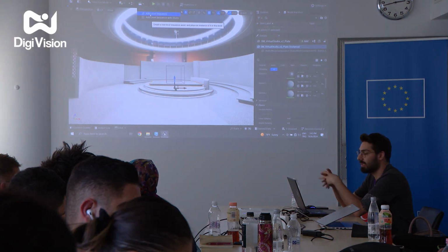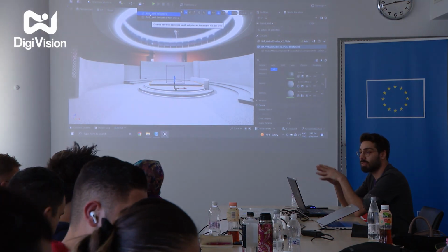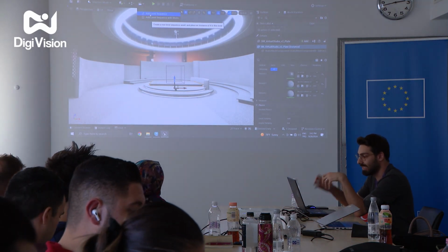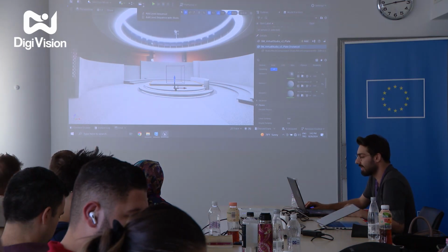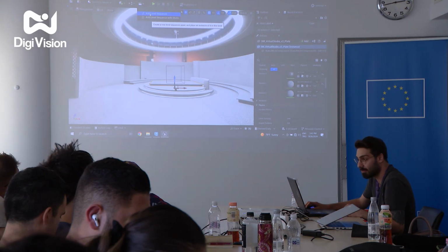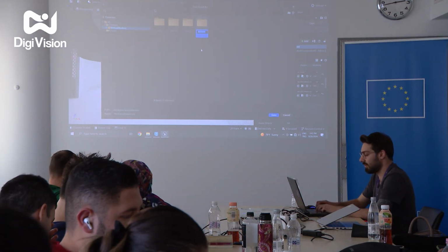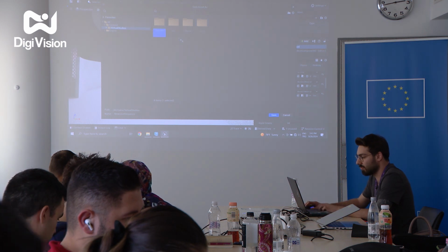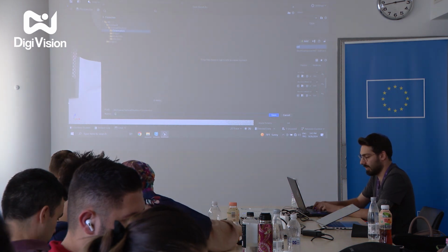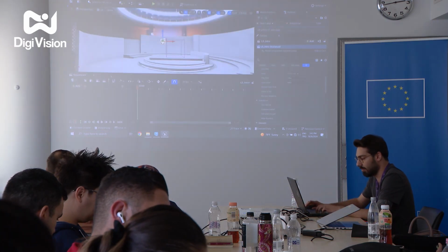We can directly manipulate the transforms of a mesh, or we can directly play with parameters in the level sequencer tool easily. So I am going to hit this button to add a level sequence to my content browser. Let's create a new folder called cinematics, maybe with the LS prefix, and I will call it intro, for example.